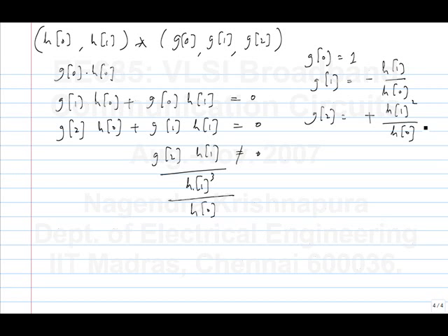This is H0 square or H0? H0 square, right? Is this okay? How equalization works? If you have more and more taps, you can reduce it. You can never reduce it to 0 with a finite number of taps, but we can make it small enough. Because if this is the intersymbol interference, then it is multiplied by H1 by H0 to the n minus 1 if you have an n tap filter. So this is the residual ISI.